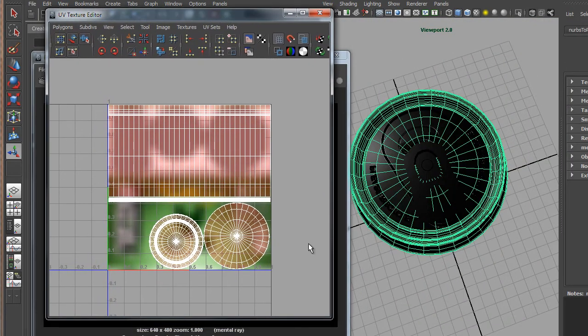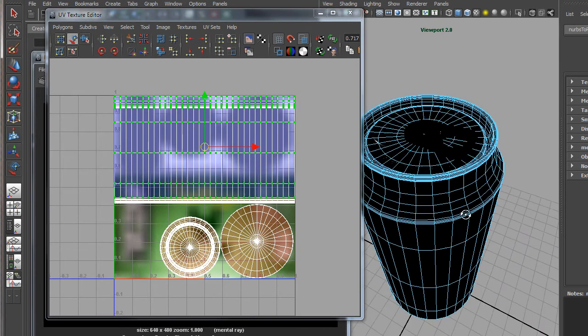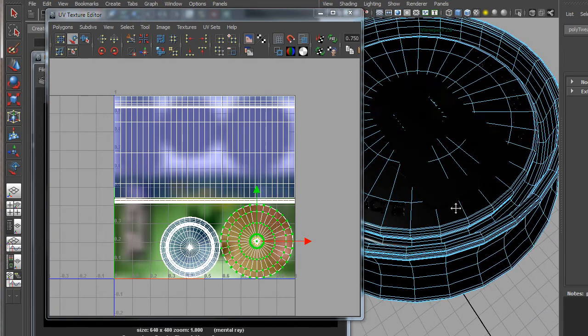Now, the last time when we created the template originally, the template was actually blue. Now, when I flipped the polygons just before using that reverse tool, it flipped these inside out. So if we now select this region using the Move UV Shell tool, we'll just click this and then press this Flip U Direction button. Okay, that's for the label down there. I'll also do the same for the other regions as well. So I'll select this bottom piece and I'll flip that in the U direction. And this one here is the one that should actually flip this around.